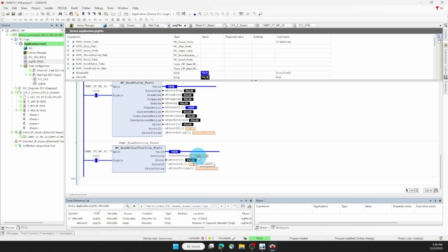So to recap, this is great for initial testing on the system. The prerequisite is just having the safety circuit satisfied and having that safety circuit closed. We need to change those parameters to set the virtual mode, and we need to change the error classification for the load voltage so that we're able to turn the motor on.